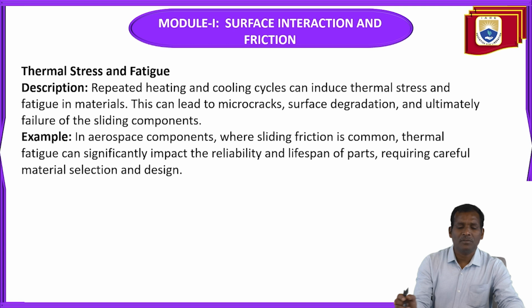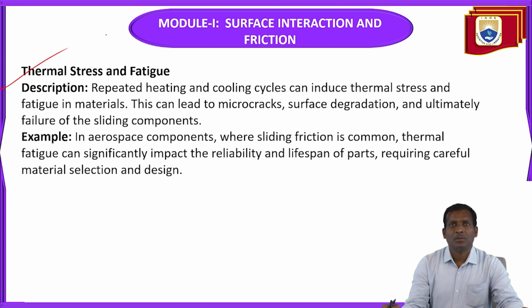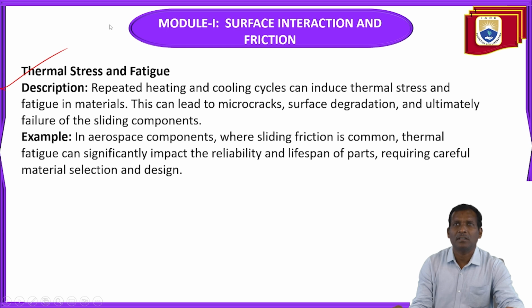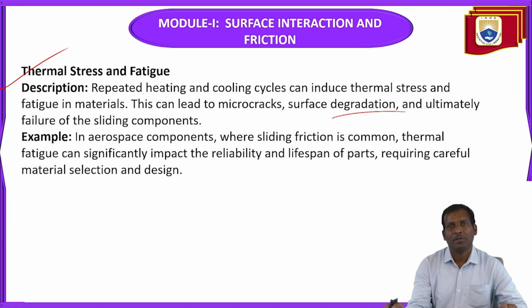So, thermal stress and fatigue. Repeated heating and cooling cycles can induce thermal stress and fatigue in materials. This can lead to micro cracks, surface degradation, and ultimately failure of the sliding components.